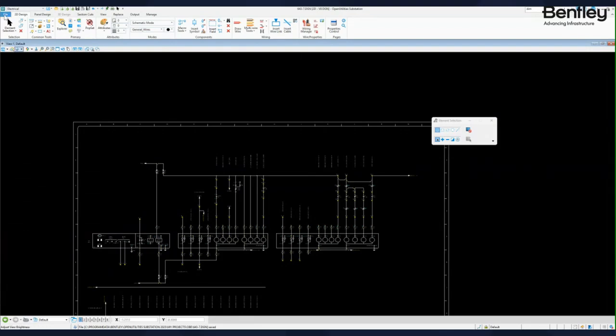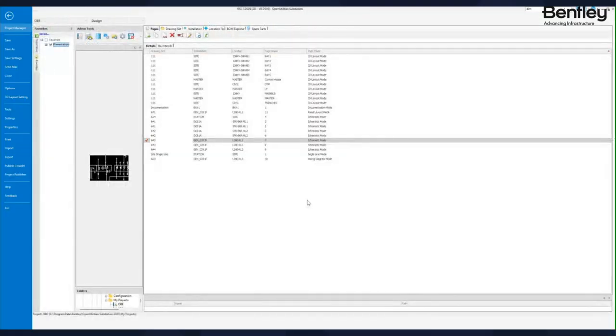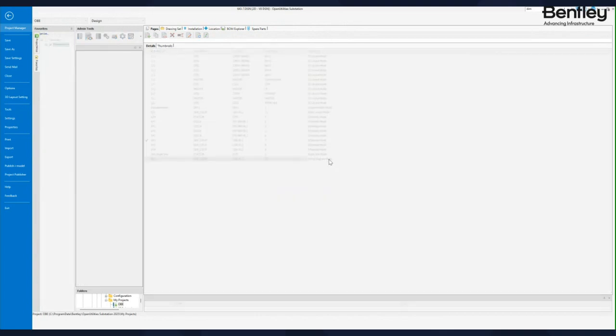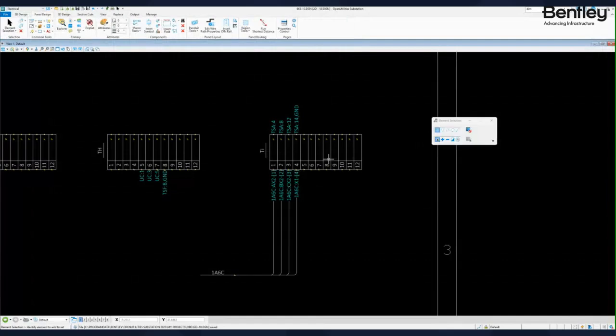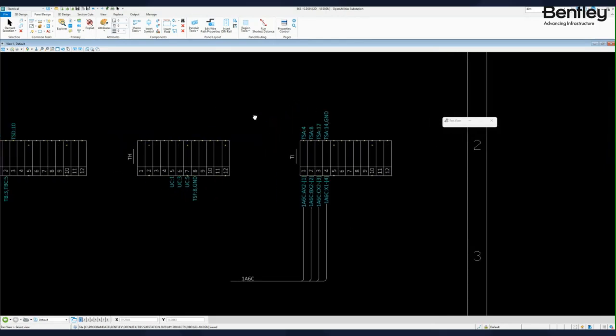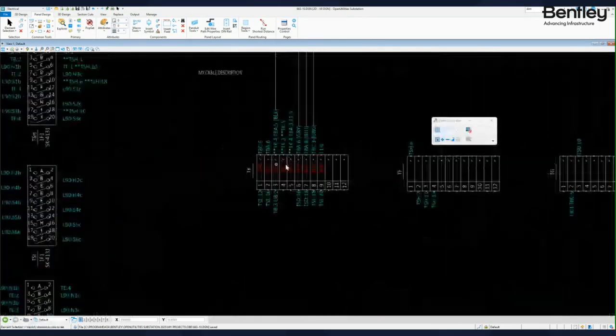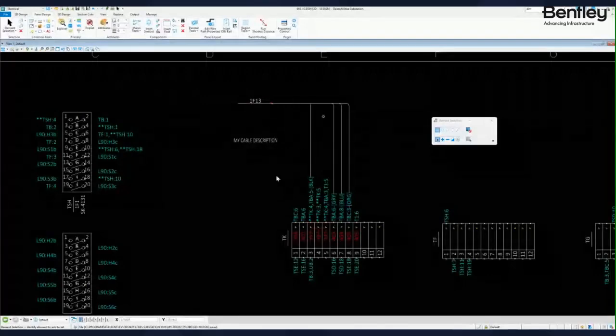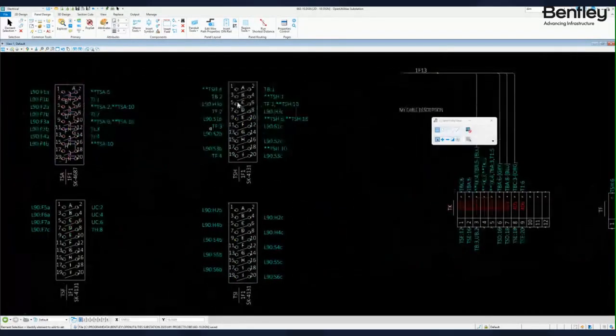Okay, then we will go to the file, open the wiring diagram mode. If it comes to the wiring diagram mode, we can simply place the symbols, and they will be automatically updated with information such as connection points, references, cross references, bridges, and so on, just like you see here, some bridges, cable description.